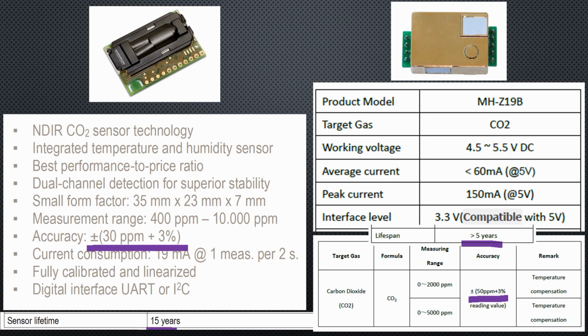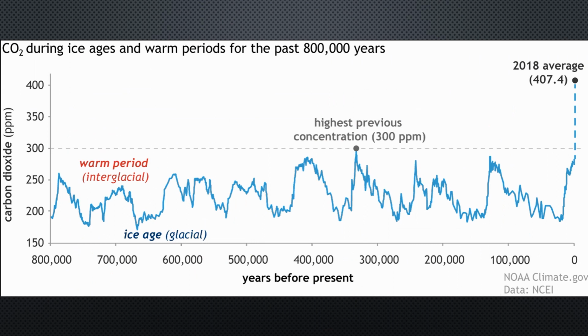And here we enter an essential area. CO2 sensors have to be calibrated from time to time. Fortunately, we can use a trick. The outside air at sea level currently contains around 400 ppm of CO2. I say currently because, as we see here, it is changing over the millennia. So we might have to calibrate our sensors to a higher value in the future. More important, this value is reduced by about 3% for every 1000 feet or 300 meters altitude. If we want better measurements, we have to do this compensation already now.